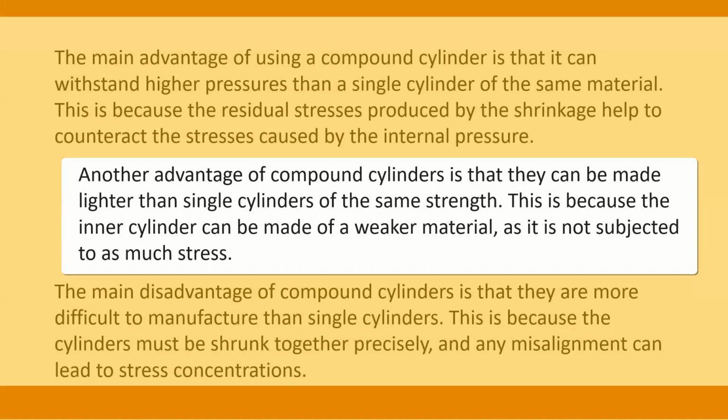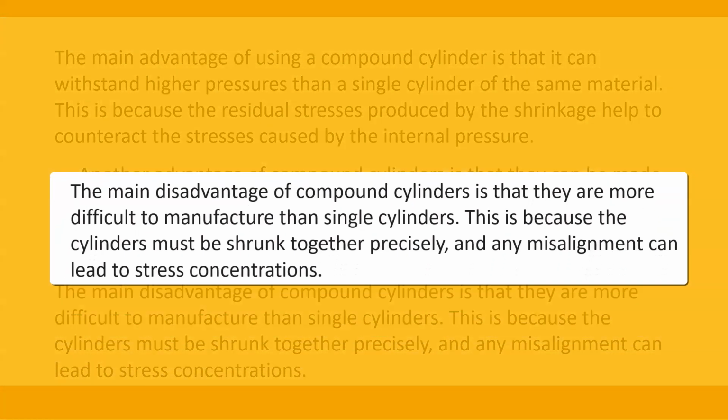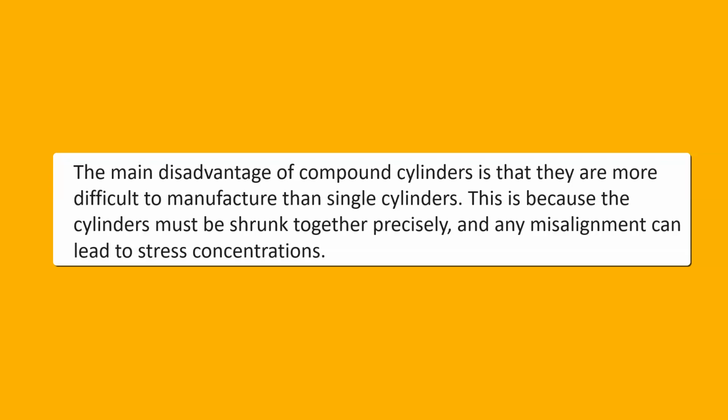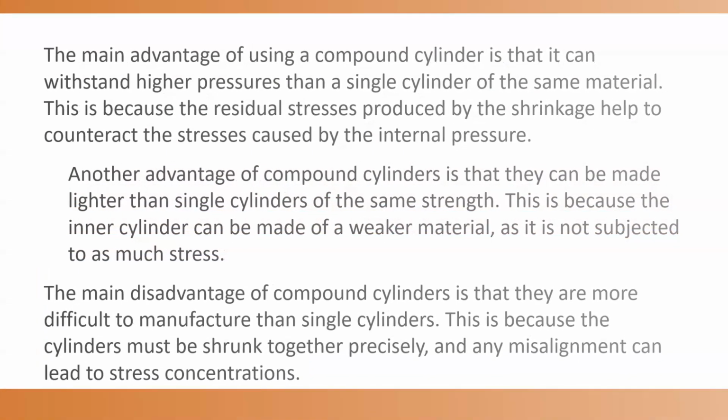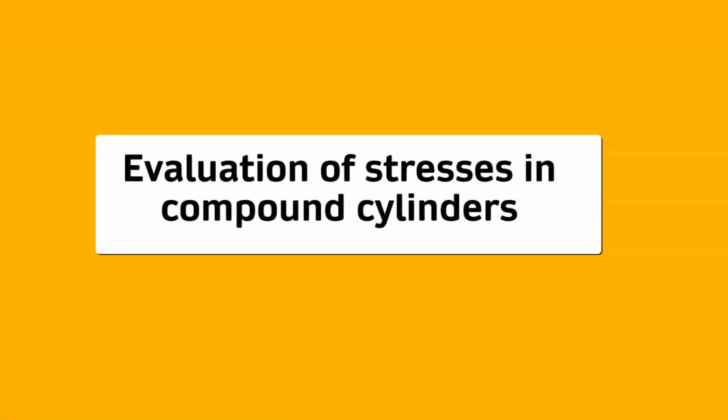to as much stress. The main disadvantage of compound cylinders is that they are more difficult to manufacture than single cylinders. This is because the cylinders must be shrunk together precisely, and any misalignment can lead to stress concentrations. Let us see how to find out the stresses induced in a compound cylinder.